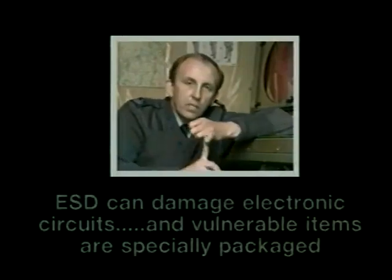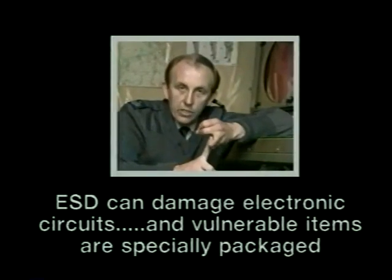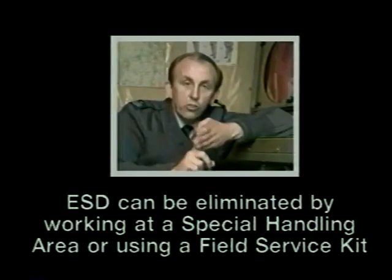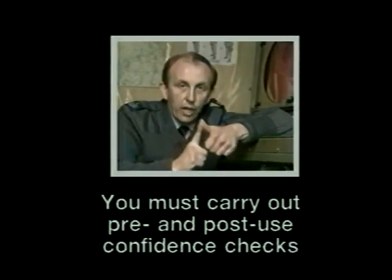Right then, let's just see if I've got this straight. ESD can damage electronic circuits, and vulnerable items are specially packaged. But ESD can be eliminated by working at a special handling area or by using a field service kit. And you must carry out pre- and post-use confidence checks. Very good. I think I'd better try again.